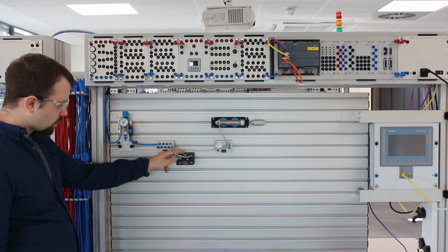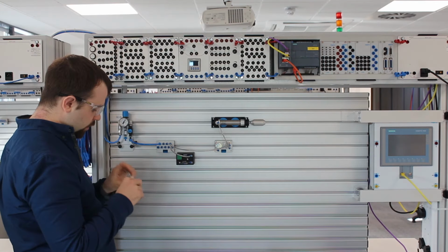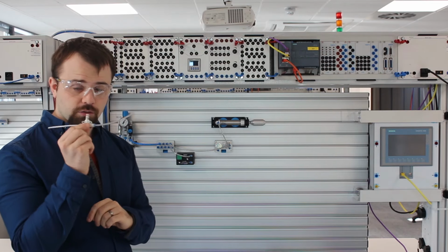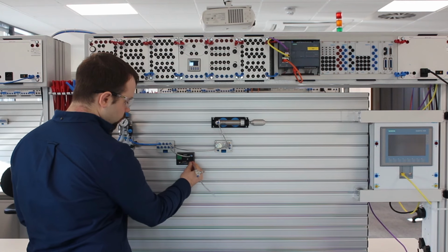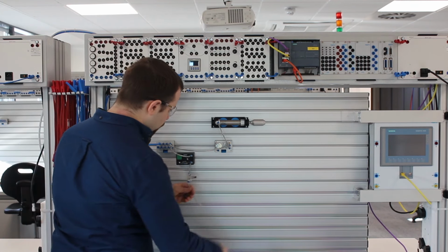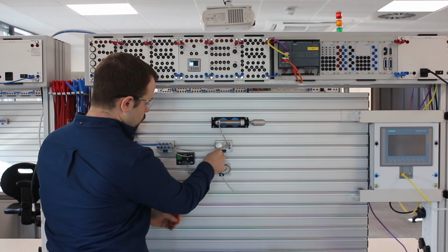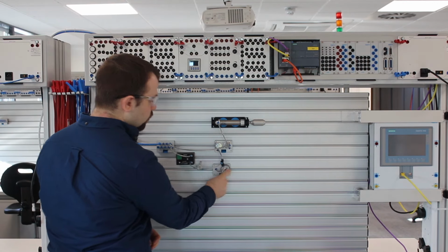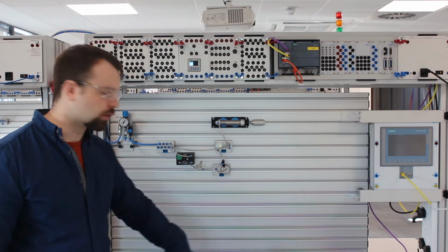So I've set up another switch with our air, and what we're going to do is we are going to limit the flow of air using one of the flow restrictors from the previous example. We're going to limit the air coming out of 2, and we're going to pass it into 1, 2, and also just into a gauge, just so that we can monitor the build-up of pressure. We don't need the gauge, but it's there so that we can monitor what's going on.